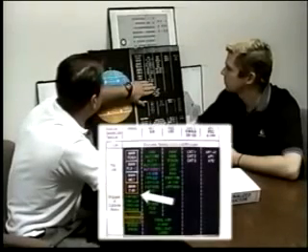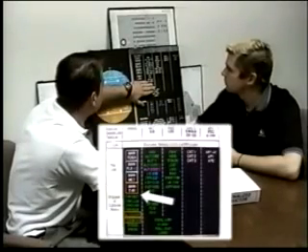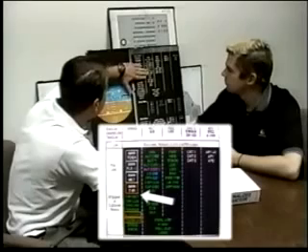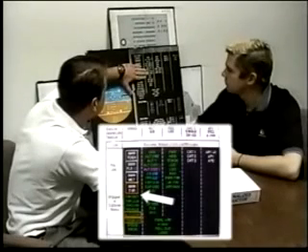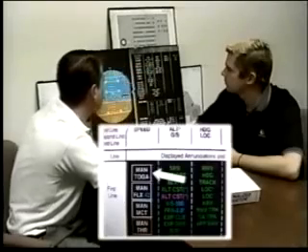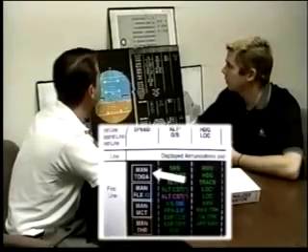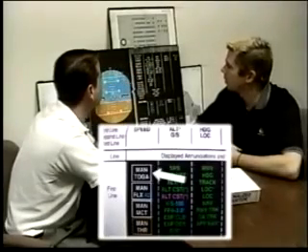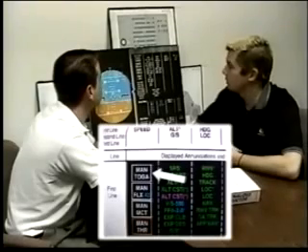Start with the auto throttle column FMAs. Easy way that I remember it is that everything above my hand is arming modes of the auto throttle, and below my hand is engagement modes of the auto throttle. So starting with the top, how would you get Man Toga? Man Toga means that the auto throttles or auto thrust is armed, and the most forward throttle or thrust lever is in the toga detent.